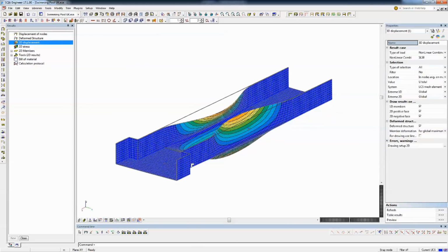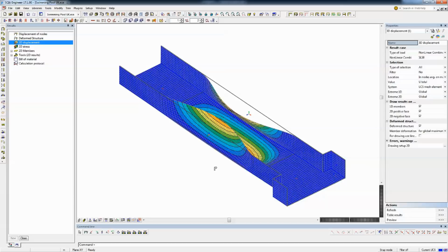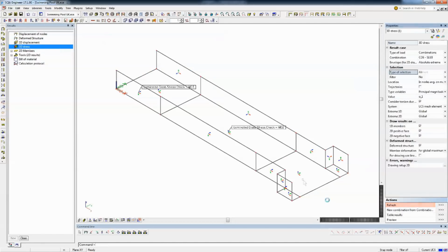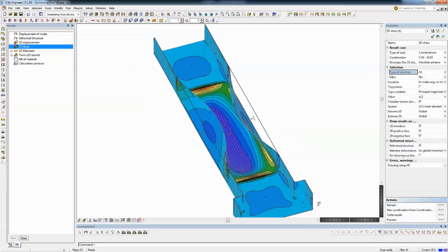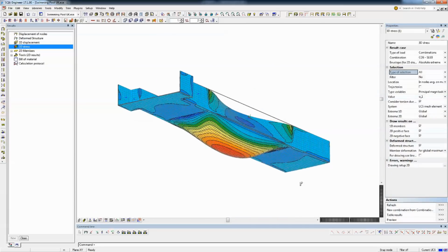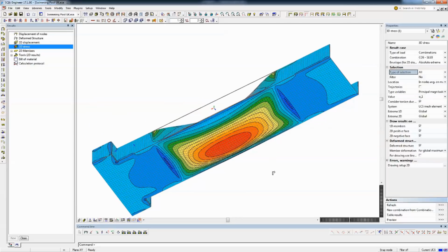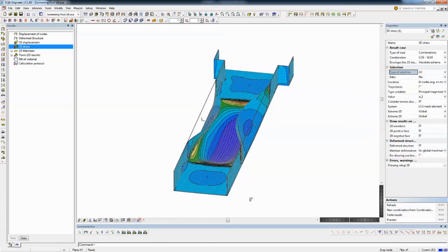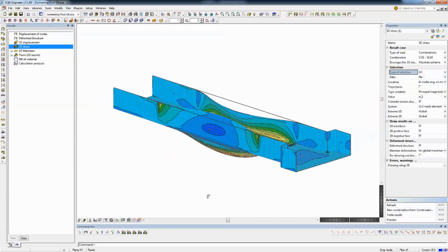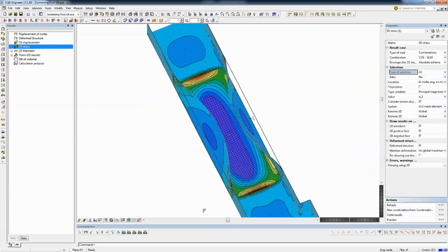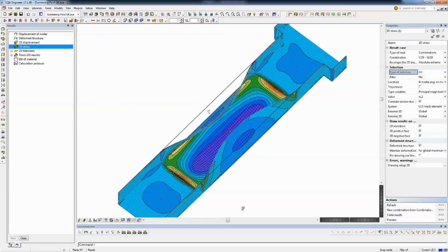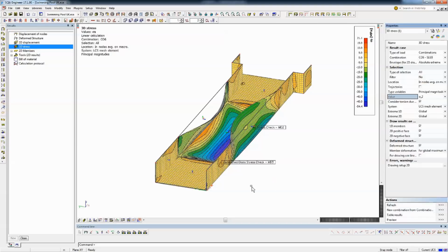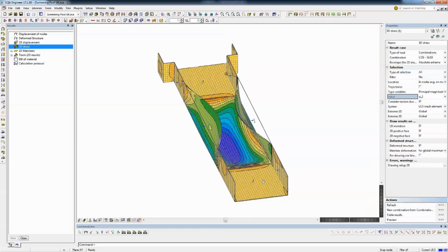And we can see here, have a look at the displacements. Maybe they look a bit strange. They are due to the wind that I have applied sideways. And it's like an envelope of the biggest deflections. And also we can see here the stress distribution in each finite element on the deformed shape. So again, although it's a single layer shell, I use the effective thickness calculated with that converter that I presented before. That converter offered me the solution to know what the effective thickness is,